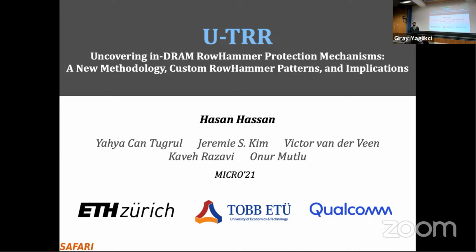Yeah. So one option is definitely to do it randomly, right? So maybe not completely randomly, but you know that a row will be refreshed every 64 milliseconds or 32 milliseconds, whatever. So you can basically perform your attack at different times within this 32 millisecond window. So this is one approach. Another approach is actually synchronizing with the refresh commands that refresh the particular row that you're attacking. That is not that difficult. And we do not discuss that in our paper in detail, but prior work shows that.